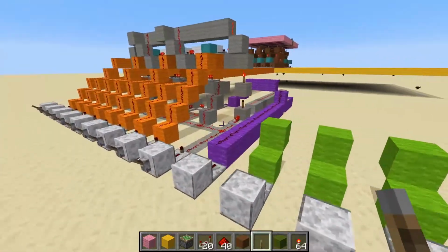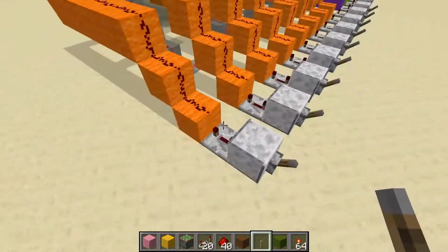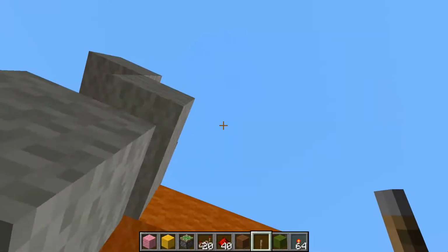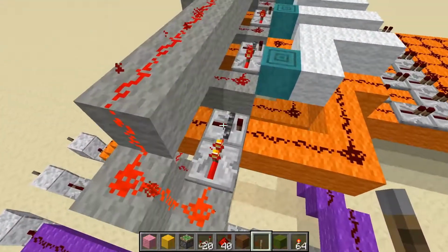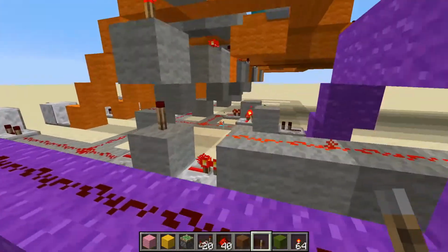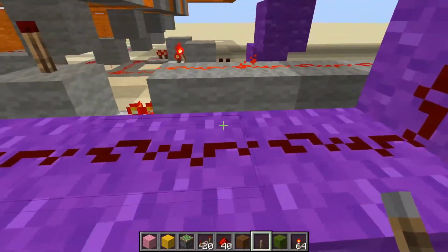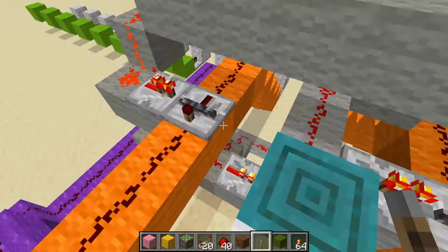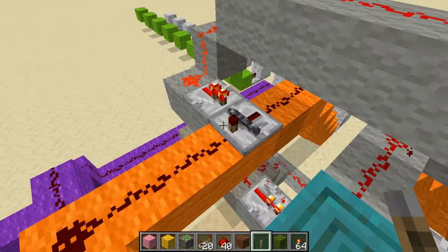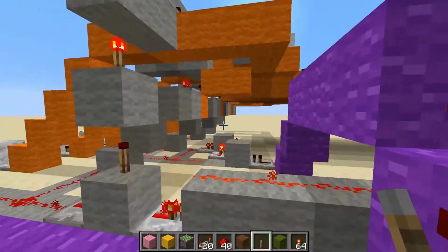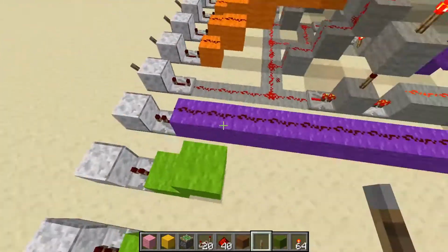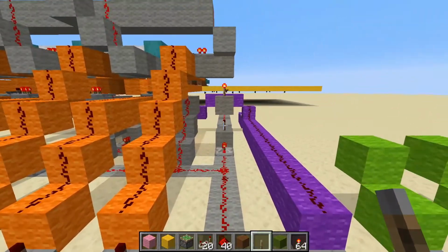What I've basically done is a bit of internal timing. We extended the pulse of the input, so the pulse is for sure in the register cells, in this gray register here, when the register saves the address, because the address has to be in there for the register to save it. So yeah. And we have extended the pulse length of the read a bit.